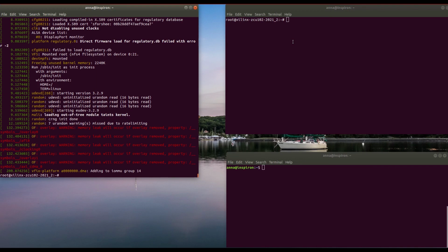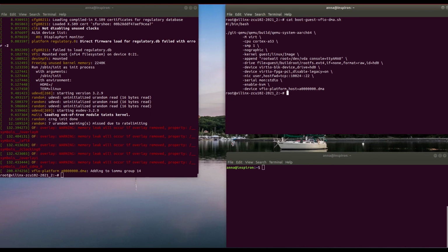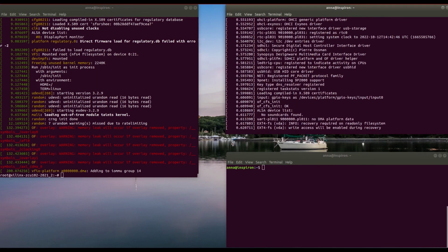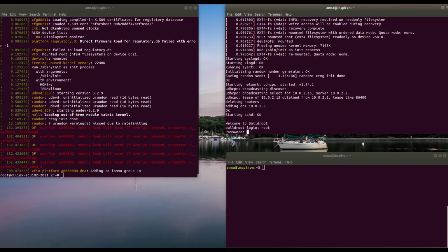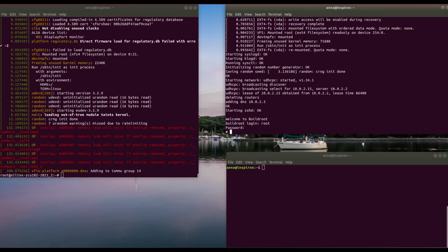So we are now in place of booting a guest image. QEMU parameters should include both the virtual FPGA device and the pass-through device, which is the CDMA one. We are now inside the guest, and first thing we have to load the VirtIO FPGA driver that will enable the interface to do FPGA programming requests in the virtual device.